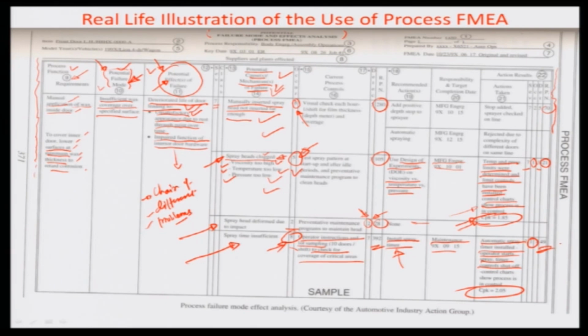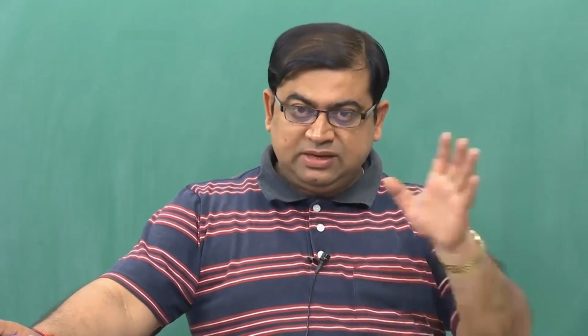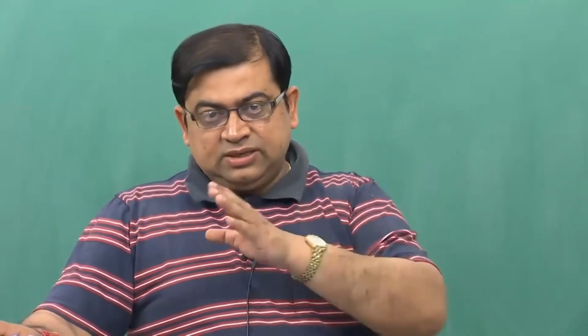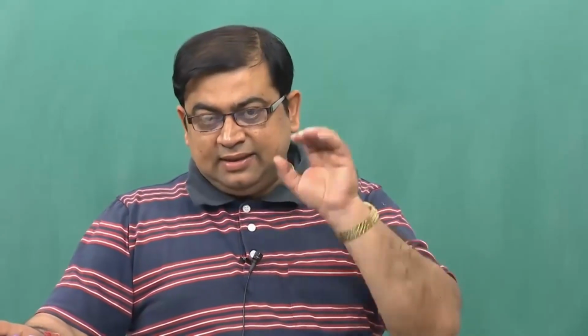So in a way what you have done is you have identified the three top causes and you have taken countermeasures to the three top causes, and with the RPN sequence you are trying to see if the RPN is getting reduced. So is there complete effectivity or efficacy of the control that has been introduced, or the new process modification that has been introduced, which will not allow the particular reason or the cause of the failure to happen, so that the overall failure goes down because of that.